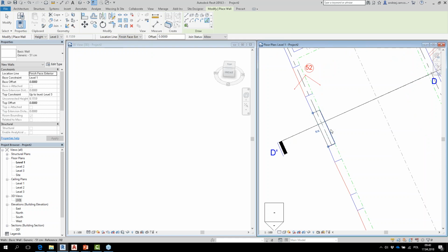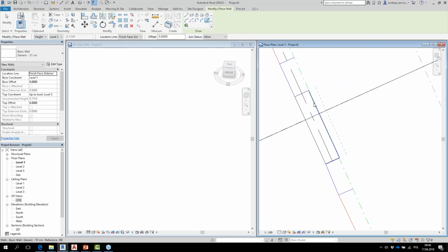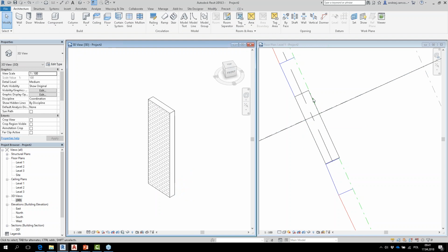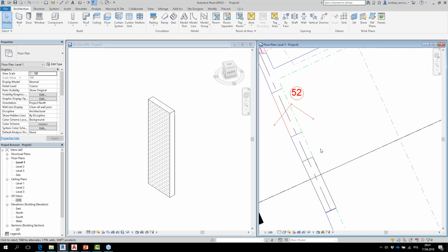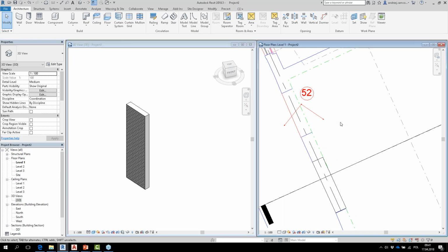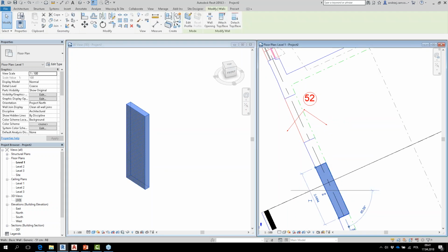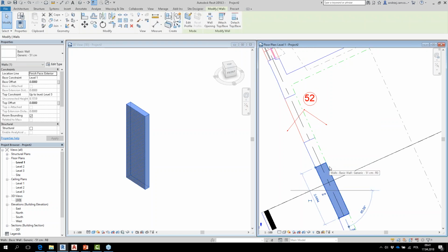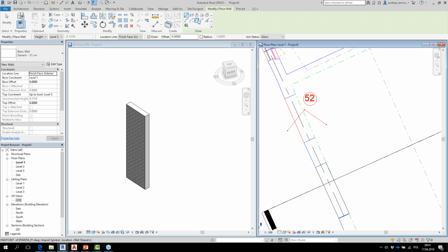Look what happens. I just picked my line. I'm gonna switch to 3D, and look what happened. Revit immediately started to place an element in 3D view as well. I'm gonna put maybe shaded view so it's more visible. And what next? I'm gonna just hit create similar, select again pick line. Of course I can also go create similar, and just start to draw this line manually, okay?